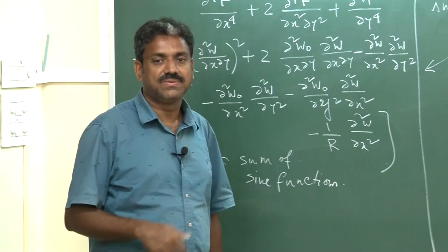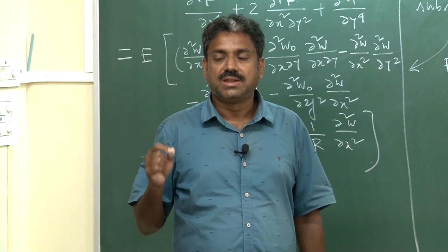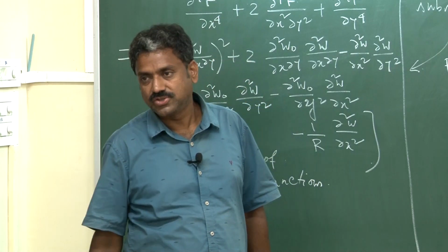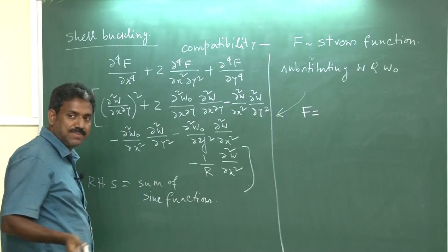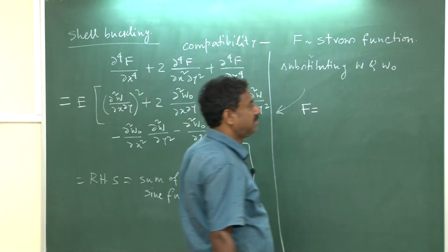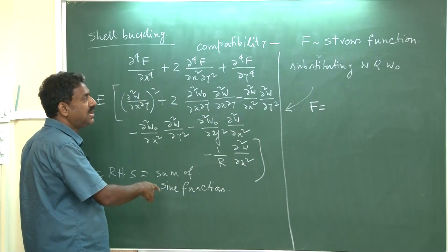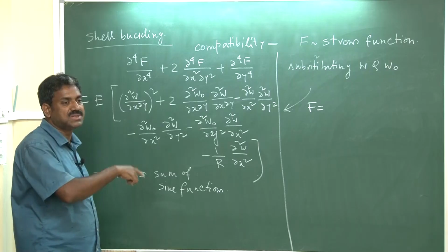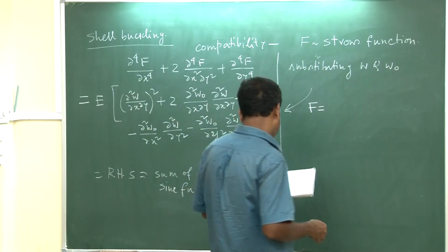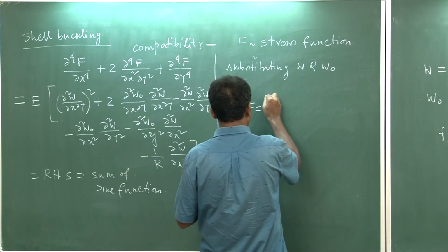The places where the series solution technique is particularly useful are differential equations with variable coefficients. But here they are not variable coefficients, they are all constant coefficients, but nevertheless it is applicable here also. Once again, let me reiterate: you take this function and substitute it, so the right hand side becomes a function of sinusoidal terms. Then you assume the solution to be a series of sinusoidal terms, and equate the coefficients. So, I will finally write the stress function. You will get the stress function to be E.